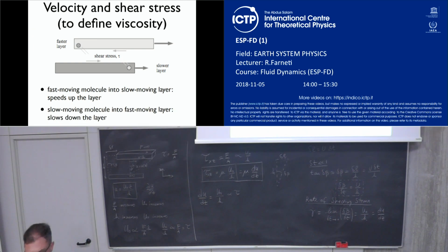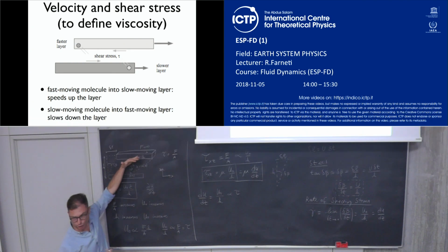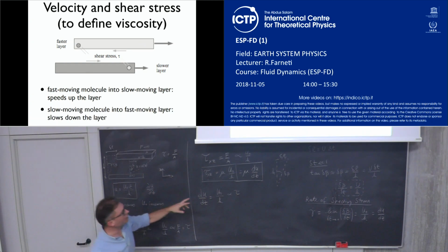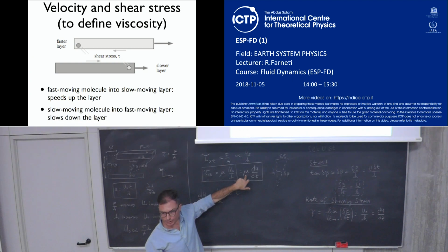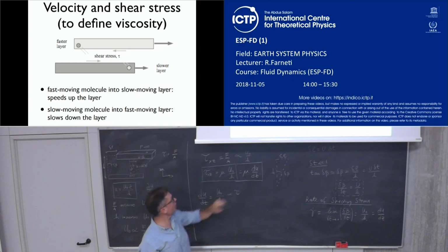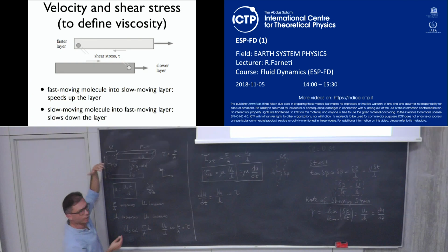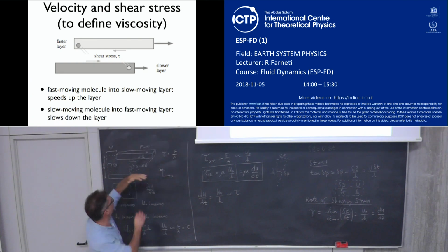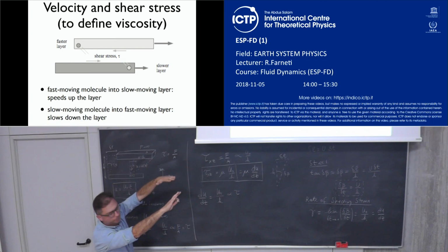But it also depends on the fluid, because you might have the same shear stress on the same fluid, and you will develop a different velocity gradient. And that's because every fluid has a different mu. Okay? So in water, you have a shear stress, the water deforms very easily, and you have a strong velocity gradient.